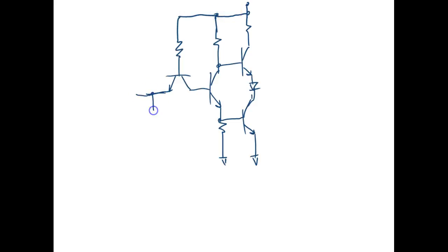And then they put a diode right here to protect the input from ever going negative, because that could really cause some problems. So this is a standard TTL inverter. Fortunately, we represent it with this symbol right here.